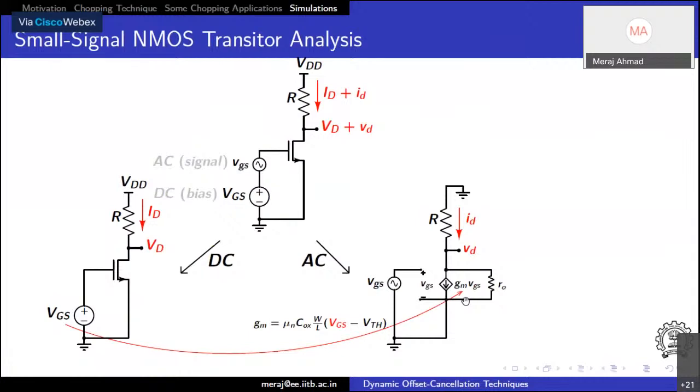So now, what is the difference between simulating this type of circuit and with a chopper? The moment we put a chopper, we are just changing the schematic with time. So in that way, we cannot have a single DC operation and calculate the noise and AC, and every simulation can be done. For that, we need to do PSS analysis, periodic steady state analysis. The idea behind PSS analysis is, in our case, since we are using a square wave, it has only two states.